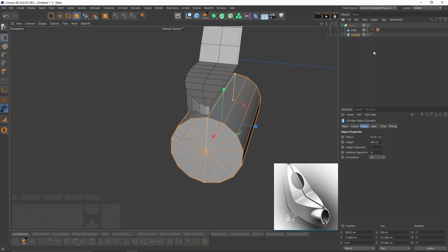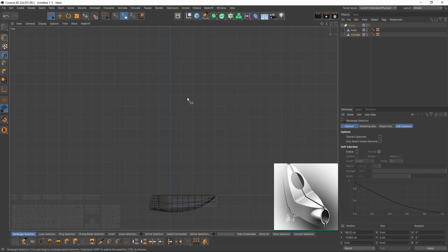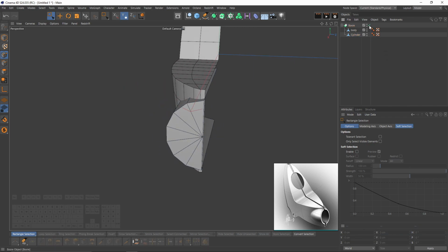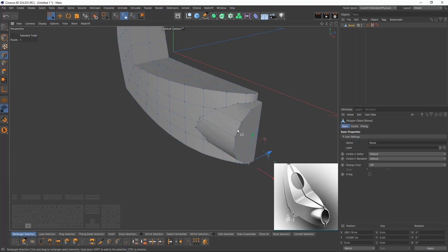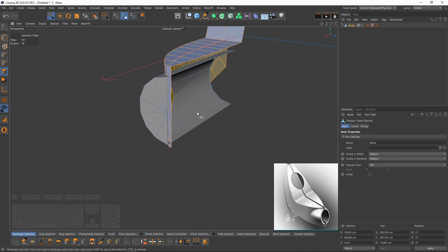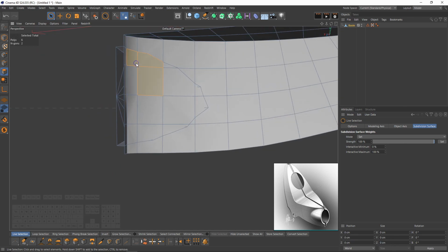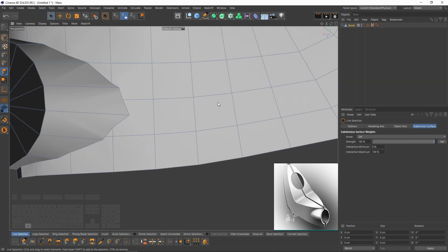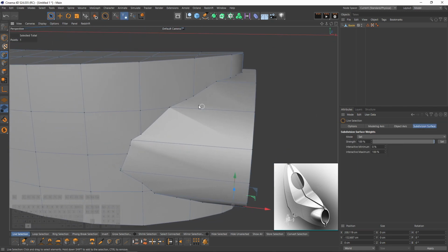Actually, we can make the cylinder editable before making the bool editable, and delete that side of the cylinder. And we can delete that point as well. Let's enable bool and simply make it editable. Press C. We will need some cleaning like these ones and these, not that and that. Delete them. Now I need to do another cleaning, and it's going to be points.